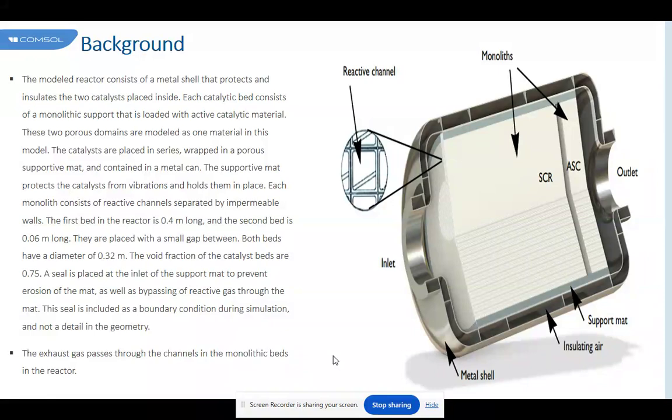First, full depletion of the CO was reached in the two substrates with a 900 per 2.5 monolith in the core. On the other hand, independent of the position, the parts of the substrate with a 400 per 6.5 monolith didn't reach 100% conversion. A 900 per 2.5 monolith has a higher geometric surface area than a 400 per 6.5 monolith.